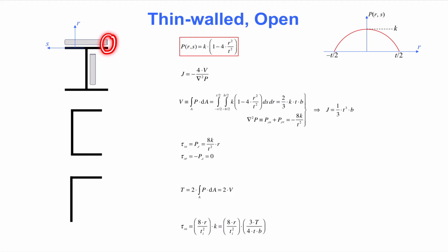on Saint Venant torsion in the short course on structural members. However, this stress function remains appropriate as long as the thickness, t, is small relative to the length of the cross-section parts. The second equation shows the expression for the cross-section constant, J, derived earlier.